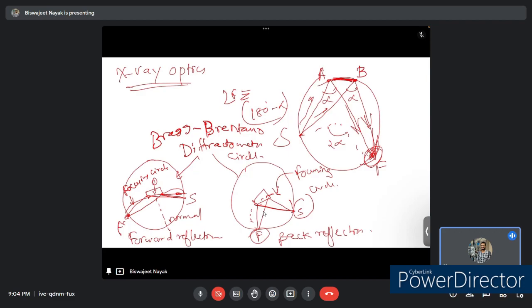Perfect focusing at F requires that the specimen be curved to fit the focusing circle. The use of a flat specimen causes more broadening of the diffracted beam at F and a small shift in line position towards smaller angles, particularly at 2 theta angles less than about 60 degrees. Both effects can be lessened by decreasing the divergence of the incident beam, at the expense of decreased intensity.